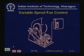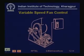What is the third method? The third method, which is a very energy saving method, is variable speed fan control. You don't put any damper, but rather change the speed of the fan and reduce it when you require less flow. But for that you require a variable speed drive of the motor, and much more sophisticated technology is required, especially when the motor is large, compared to dampers or valves. But as we shall see, they can save a considerable amount of energy.